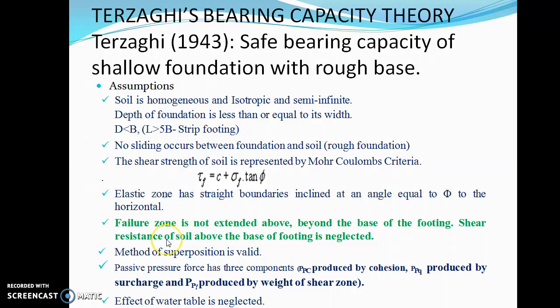Now this is applicable for shallow foundations. What do you mean by shallow foundation? It is that the depth of the foundation will be less than the width. It is also applicable for strip footing. Now what is a strip footing? When the length of the foundation is greater than 5 times the width, then it qualifies to be called a strip footing.